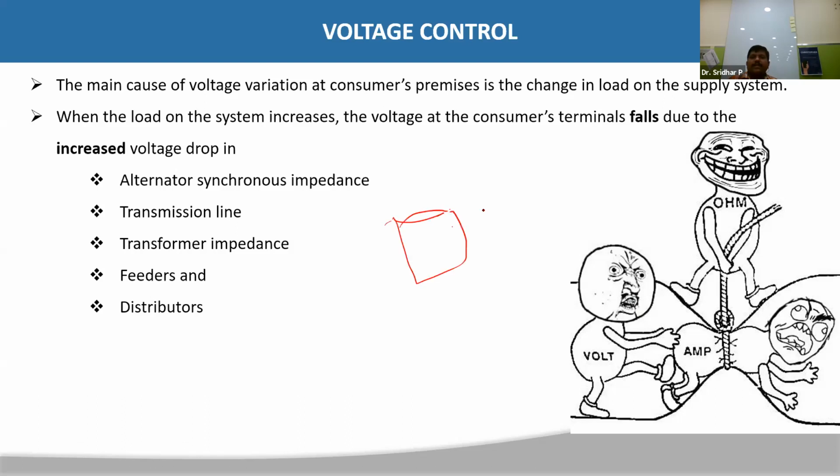This is called a capacitor bank. What is the need for these capacitor banks? Capacitor banks supply reactive power to the system. If the reactive power is properly maintained, then the voltage will also be maintained properly. So these capacitor banks ultimately ensure that the voltage is constant.